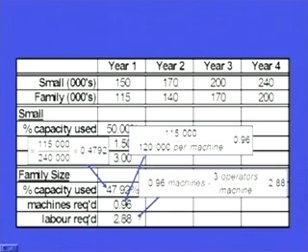So labor required can be calculated as 0.96 machines, which we have got from here, multiplied by 3 operators per machine required for family size bottle machines. So we find that 2.88 operators are required. 2.88 is not feasible, so 3 operators are required and 1 machine is required for processing the demand forecast of 115,000 bottles of family size.